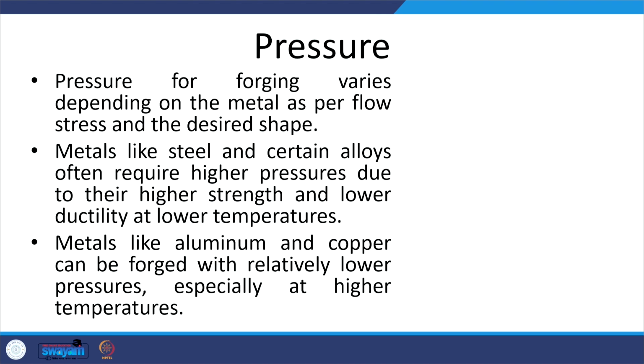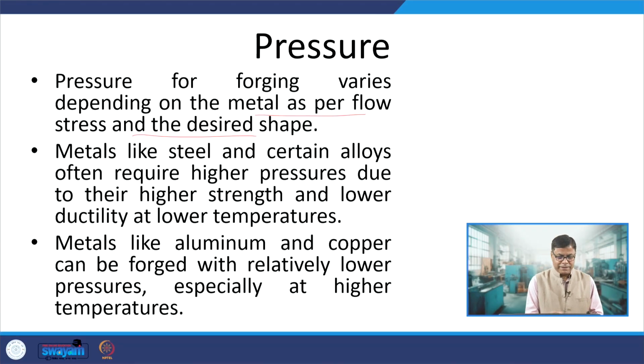Pressure for forging varies depending upon the metal as per the flow stress and the shape desired. The more complex the shape, the greater the pressure that will be required to ensure that the material flows and fills the fine cavities. Apart from that, certainly the type of the metal will significantly affect the pressure at a given temperature or for given forging conditions.